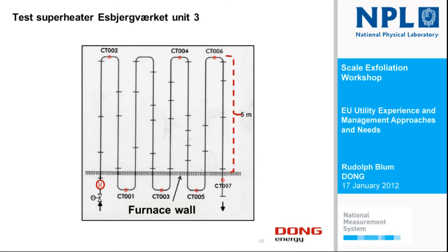And then in the final coils, we will go up to even nickel alloys, nickel-based alloys. The first test we ran for, in total, 7 years. The first superheater was taken out 1 year after, the second one 3 years after, and the last one was operating for 7 years. We had an outlet temperature of 620. Then we have an improved model, another test where we had outlet 635, and we have one at 700 centigrade, and one that was the last one taken out last year, 720.